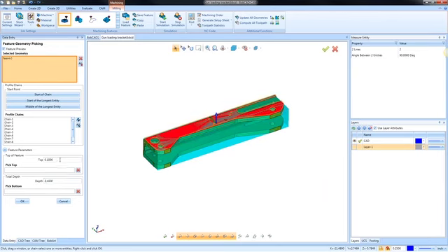Now, I don't really have any material. I haven't put any material on the face of the part here. So basically, I'm just telling it to cut to 0. But you could also have material on the top that you're facing down, if you've zeroed the top of the part. It depends on how your setup is, but generally speaking, with your face cycle, a lot of times you're going to set it to where you're facing to 0, but that's kind of up to you.